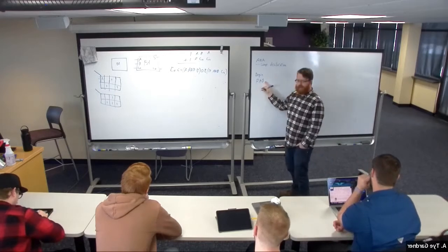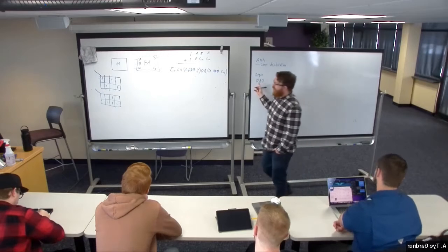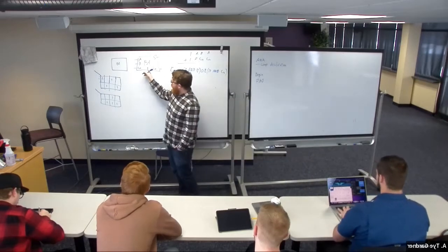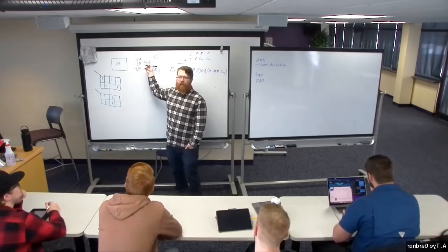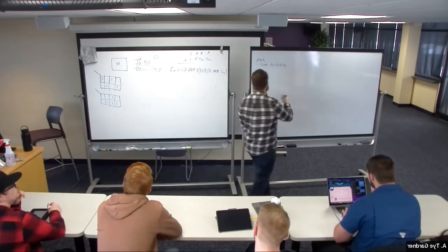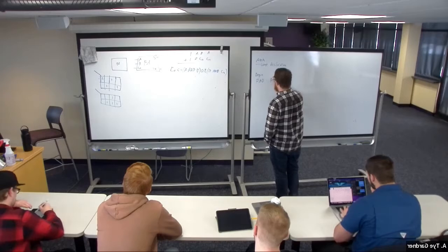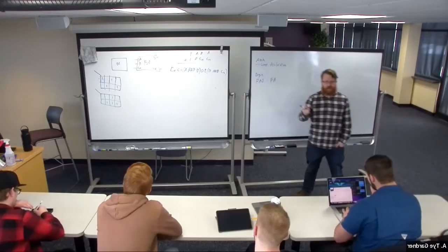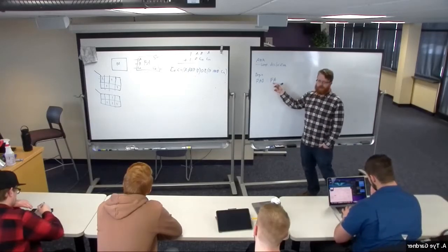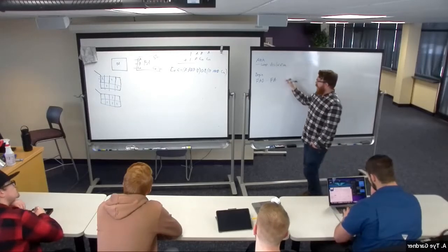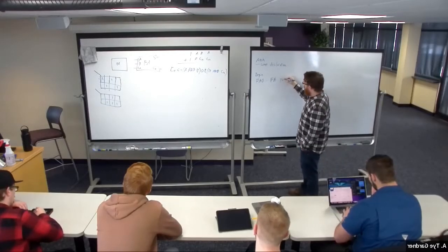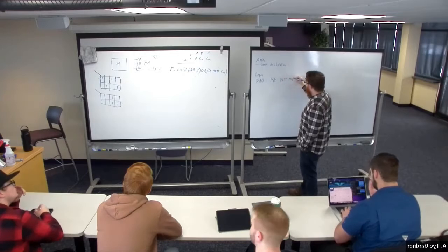This is a component name, not what type of component is it. What's the name of it? Its type, in this case, is FA. It's full adder. This would correspond to something that would be entity FA is, and then describe its ports. And then I give it a port map.